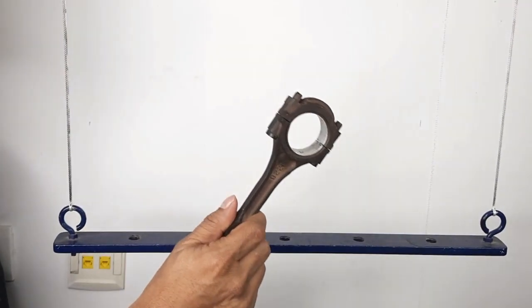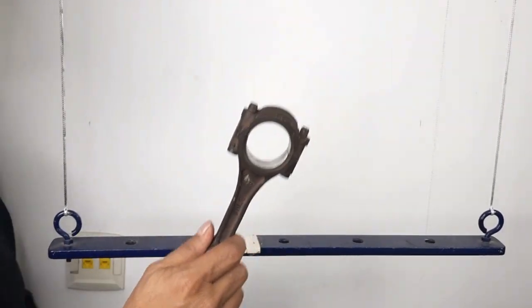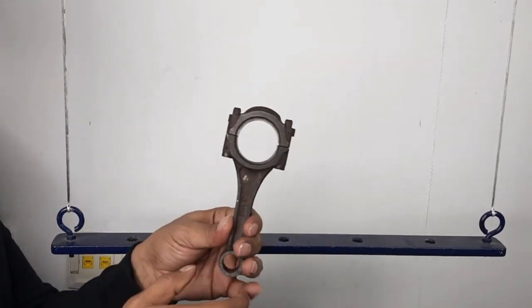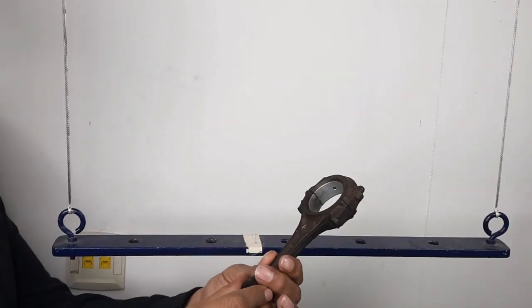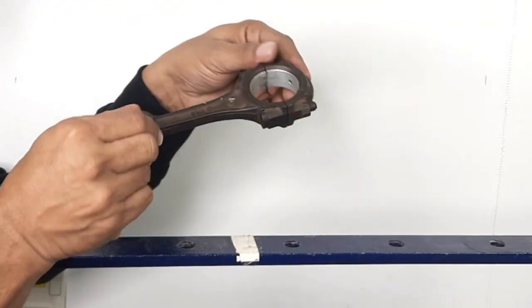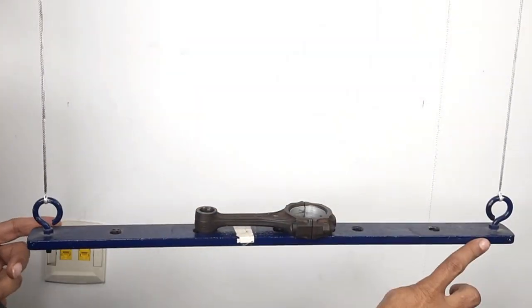The last part of the experiment is to find the K value of this connecting rod. What should be known a priori? The center of mass of this connecting rod. Assume the center of mass of the connecting rod is here, and the mass of the connecting rod is 374 gram. What I am going to do now is coincide the two centers of mass, and again give a gentle rotation.